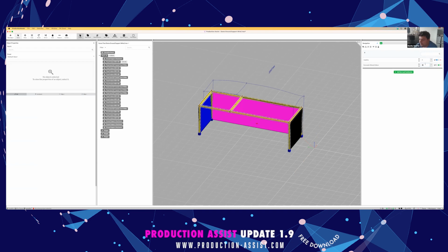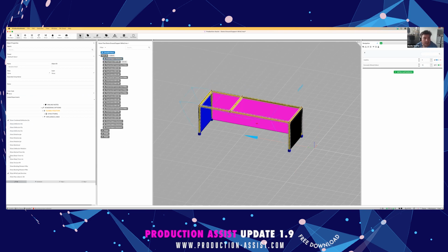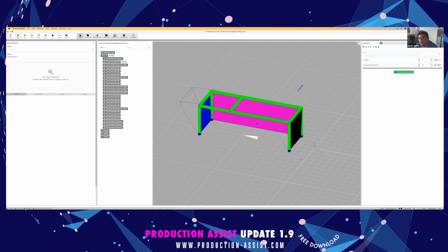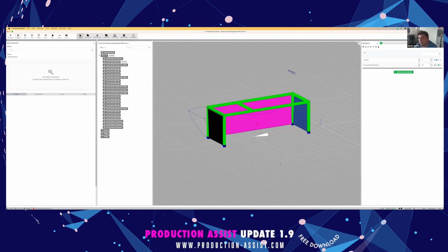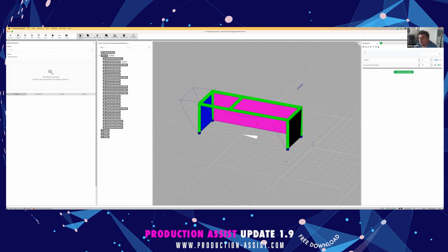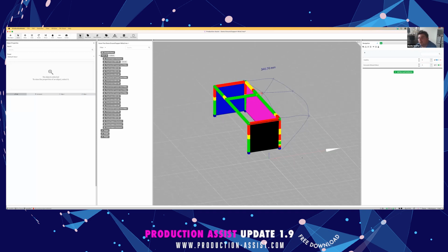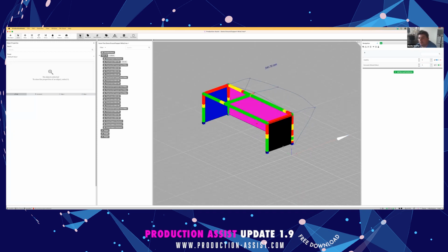The interesting part is that you can also have a look at the workload in here. If you show the workload, you see that when the wind is coming from this direction, you don't have any problems. The truss structure will actually hold everything. If you now go back and do it so that it's coming from this direction, looking at the workload really troubles you. This will not hold if the wind is coming fully from this direction.